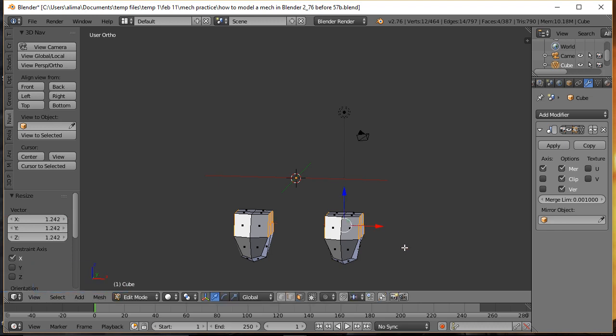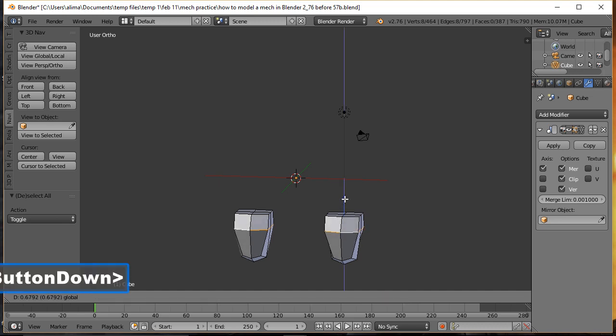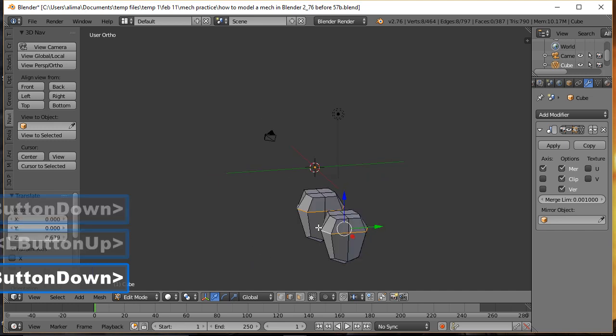Now what I'm going to do is press A to deselect. I'm going to go to edge select. I'm going to hold Alt, select right here, and I selected there while holding Alt. Because I held Alt, the entire edge loop was selected there. Now taking the manipulator to pull up some, like this. Press the middle mouse button to take a look.